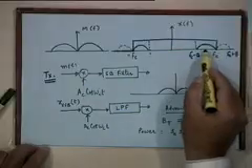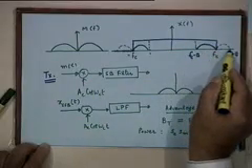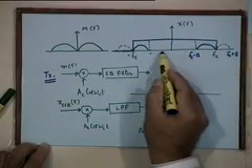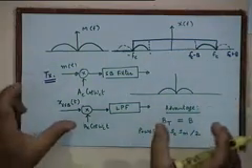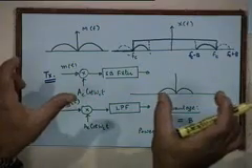You can put different messages, each of them occupying only a bandwidth of B, close to each other, adjacent to each other. I can put one message here, another message here, a third message on this side, a fourth message on this side, and so on. I can put them side by side at a spacing of only B hertz. There are methods to do that, and I can do that precisely because each of these messages requires only B hertz.